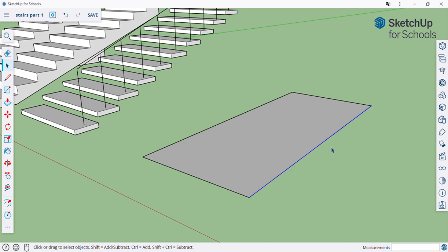These dots disappeared, sadly, by the way. I wish we could still see them. And now we're going to select this segment. We're going to use the move tool with a plus, and we're going to move this, not the midpoint, but we're looking for another green circle that is going to be exactly at 50 centimeters. The computer memorized these little red dots.